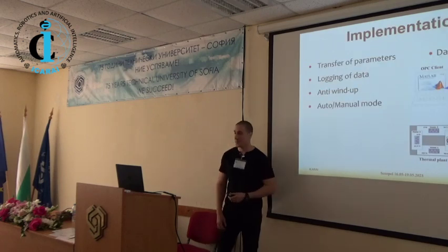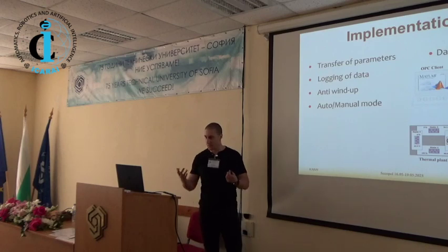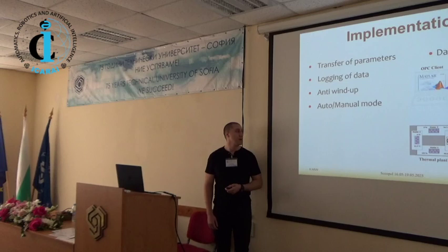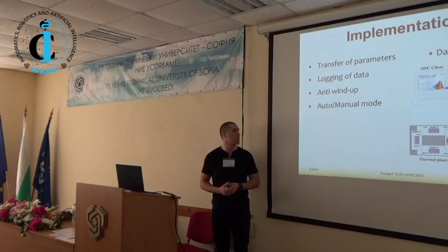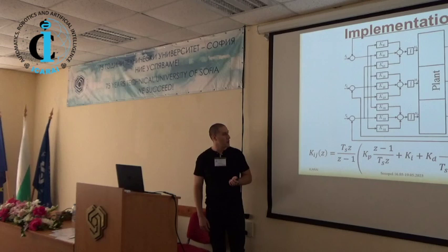What about the implementation again? As I said in the previous presentation, we control the plant itself with a programmable logic controller, so we need a digital implementation, which I'll show in a moment. Again, the parameters are calculated on a separate PC with MATLAB, then we send the parameters through the OPC connection. Again, we have an anti-windup mechanism, but this time in a different structure. I'll show it in the next slide, which is this.